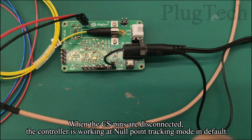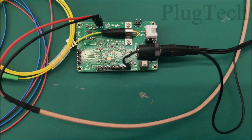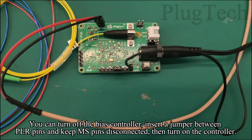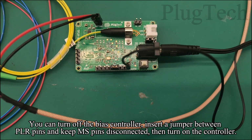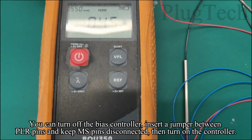When the CS pins are disconnected, the controller is working in null point tracking mode by default. If you want to switch to peak point mode, you can turn off the bias controller, insert a jumper between the PLR pins and keep the MS pins disconnected, then turn on the controller.